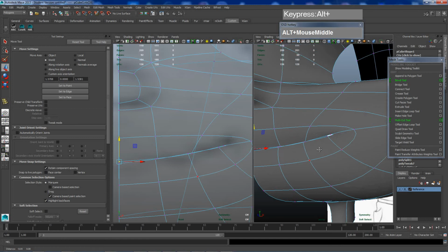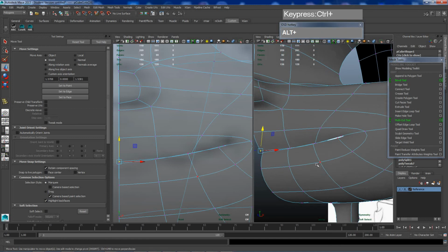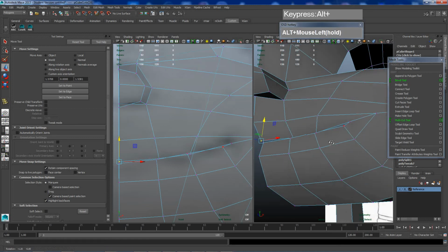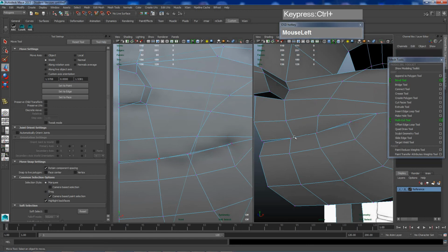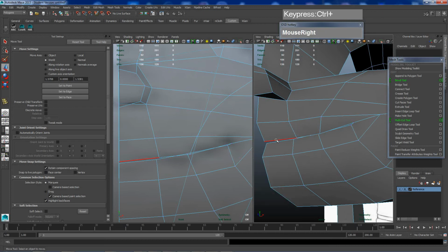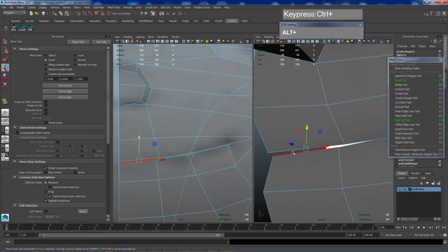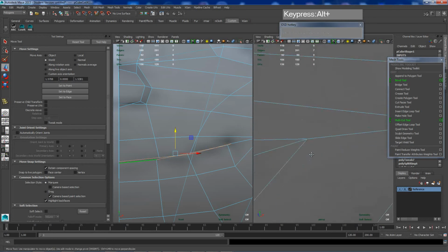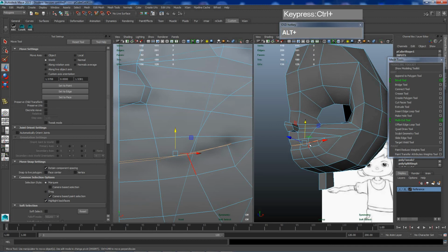Should you want to, you can actually select the open edge. If I press number 1, you can see that we still have an open edge for the lip. So I'm going to show you a trick to select the open edge very quickly. Right mouse click, go to edge mode, select this edge, and then holding down shift again, select the edge at the bottom, double click, and the entire opening will be selected. You will not be selecting the outer edges.